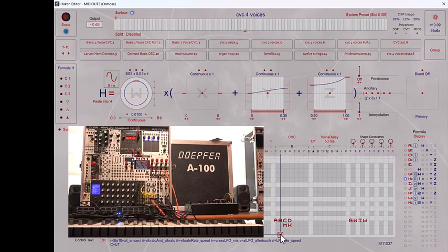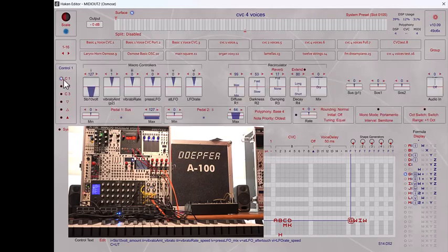If you watch our last video, we did something very similar. You'll notice that +1 has been added as an ancillary, so we don't multiply this by a very small number and get no sound because the frequency is too low. And they've also multiplied by 3 as well, so this 0.001 will actually turn into a 0.003 scaled by Y plus Z. But the bottom line is it's going to be a vibrato, the amount being the width of the vibrato set by controller 2 and the frequency of that vibrato set by controller 3. Let's give that a test.